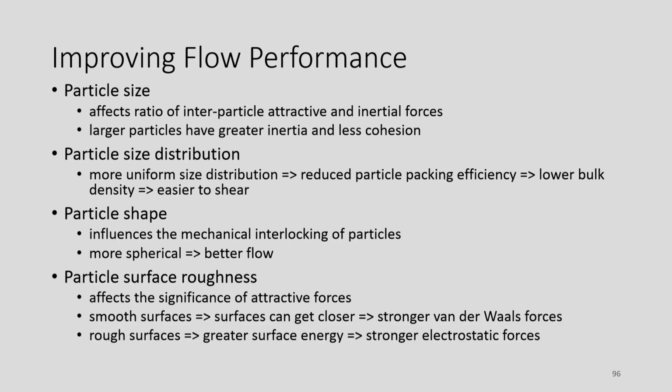Surface roughness too, I'll quickly go through. If the surfaces are smooth, there will be stronger van der Waals interaction. But if the surface is rough, there will be more electrostatic forces or static charge buildup between those particles. Either way, if the particles are small, you will have to deal with one force or the other.